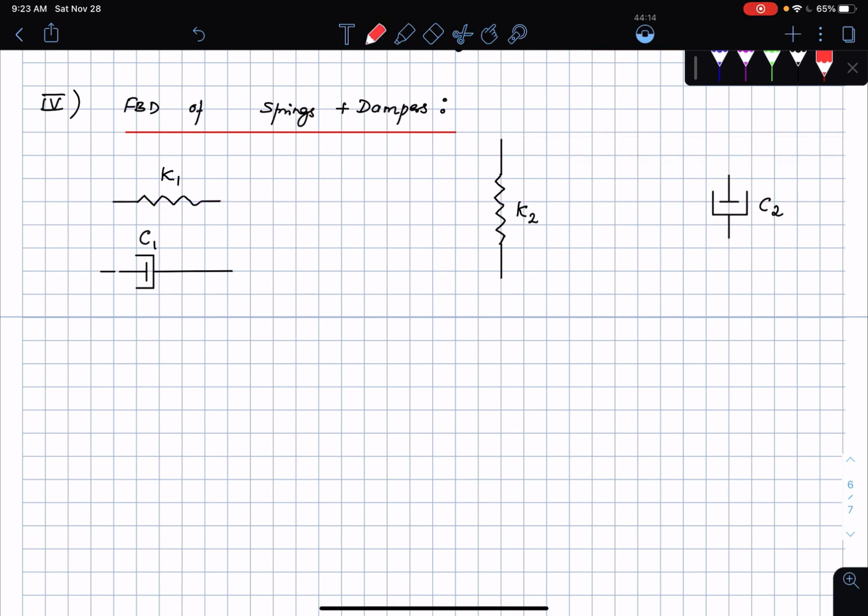Okay, and let me start writing out the forces and so on. So this I'm going to call FS1, because it's the first spring. This is also FS1. This is FD1 here, because that's the first damper. This is FD1 as well. Then this is going to be FS2, and likewise, this is going to be FS2, and FD2 lastly. Pointing this way, I guess it's going to be compressed, so I got to be careful here. This is FD2, which is going to be pushing down, based on the positive sign convention of the block. So that's something to be careful about. This is FD2.